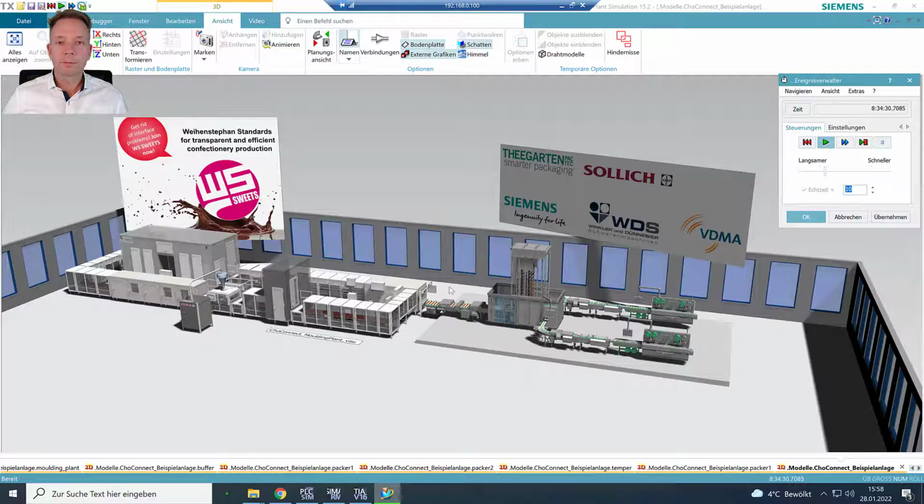And if, for example, a new product enters the buffering machine, the controller of the buffering machine can read from the controller of the molding plant what its output order is, and by this provide data with reference to the right order now processed also in the buffering machine.